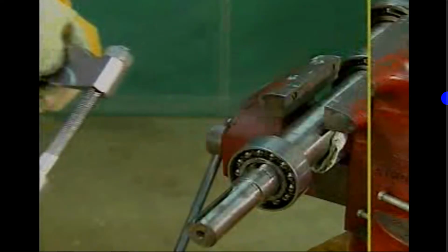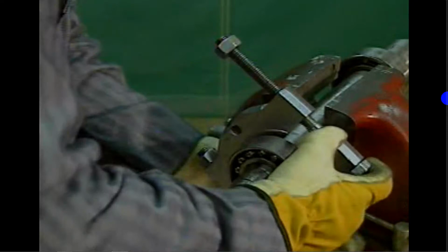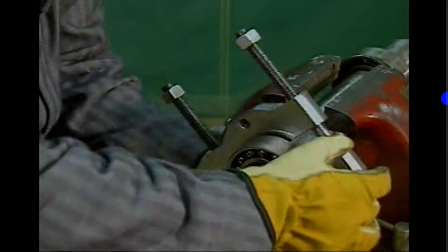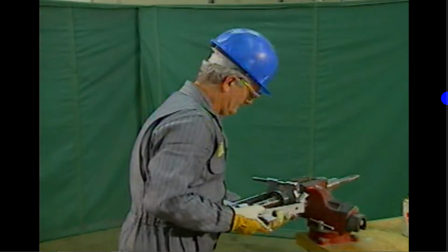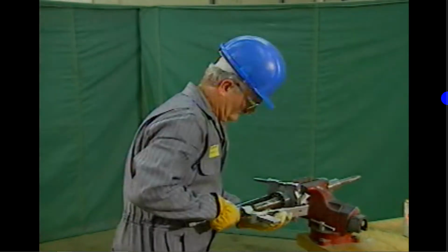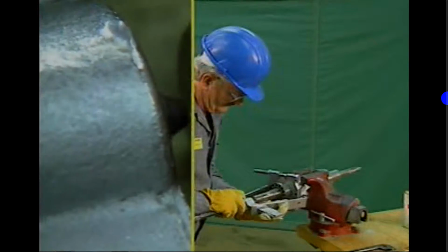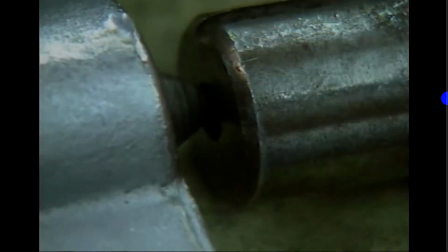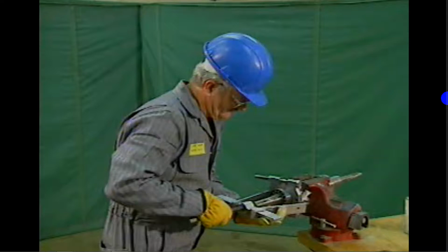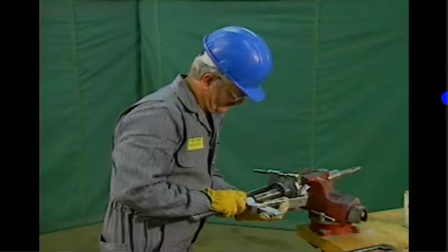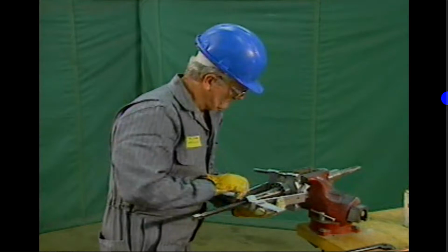Then he sets up the bearing puller jaws behind the bearing so that they rest loosely against the shaft. Next, the mechanic hooks the side rods behind the jaws. Then he makes certain that both rods are aligned correctly on the strong back. In this example, the mechanic places the lead screw into an alignment hole in the shaft. Then he tightens the lead screw. He checks the position of the jaws to make sure that they will only push against the inner ring.